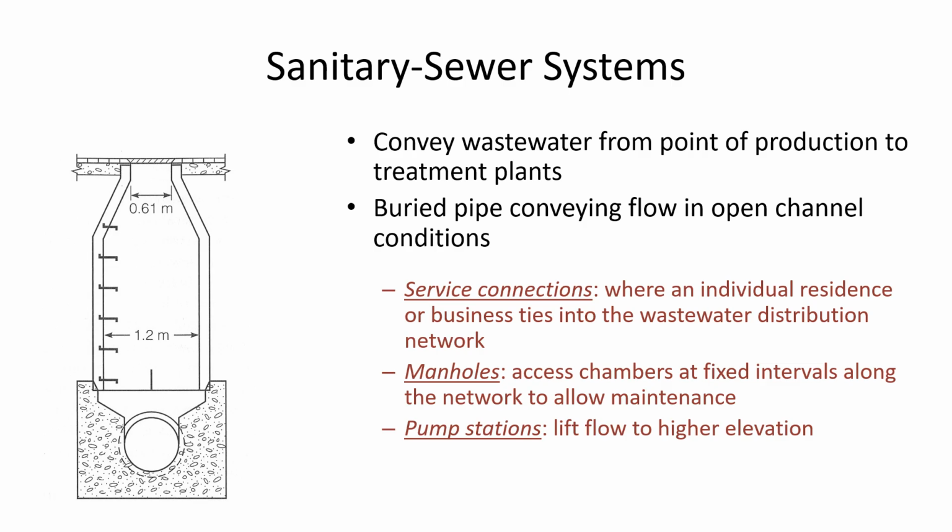But inevitably there's going to be a buildup, especially if you've got greasy wastes, like if there's oil or cooking grease that gets into the sewer discharge. It tends to stick to the bottom of the pipe. And so to prevent clogging, we have to have these manholes where people will go and inspect and clean the drains from time to time.